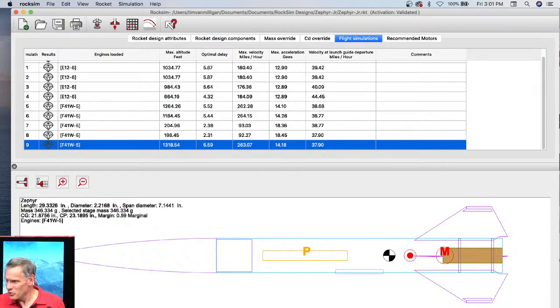Okay, so that answers Bob's question. If a rocket doesn't turn into the wind, should it be balanced to be more overstable to turn into the wind? And the answer, again, Low Budget Bob, is it's subjective. It's what you want it to do. Do you want it to be more safe and go into the wind? Or when we're marginally stable, like right here, there was that chance that it could go unstable. And so this is an engineering trade-off that engineers have to decide.